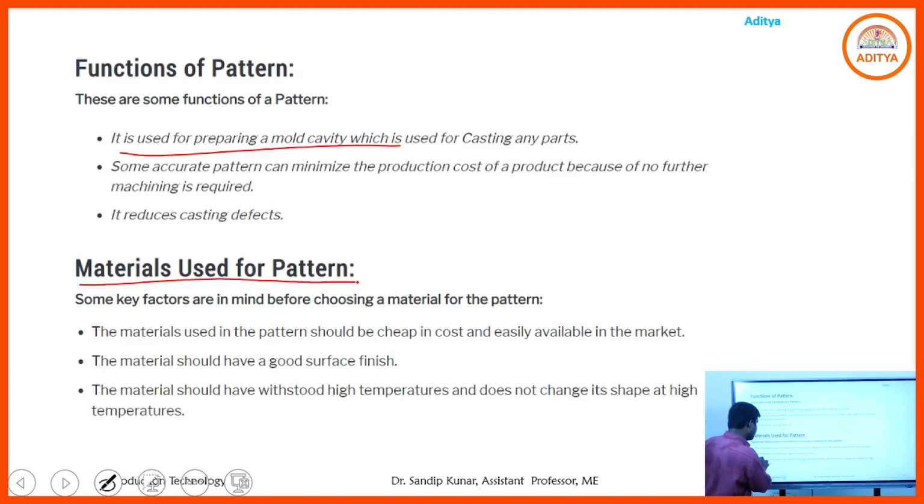Another thing, the pattern material should have a good surface finish, otherwise the outer surface of the casting product will not be good and its surface quality will be very poor. The pattern surface should always be of very good quality.